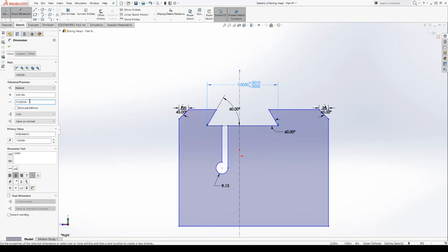So what this is saying is, if you make this part to exactly 1.5 inches, it's going to be too small, right? So you can kind of think about what that means: this is a part that fits together with another part, right? And obviously we want the internal dovetail to be a little big and we want the external dovetail to be a little small from the nominal. Well, this just basically does that. This is exactly what that's saying.